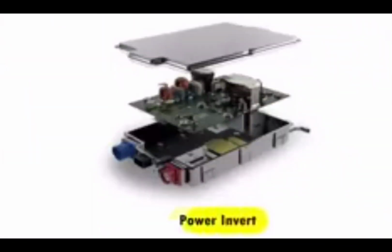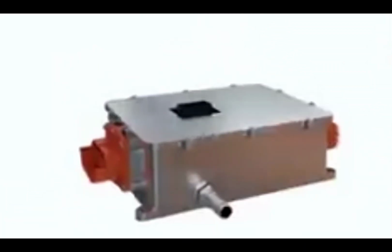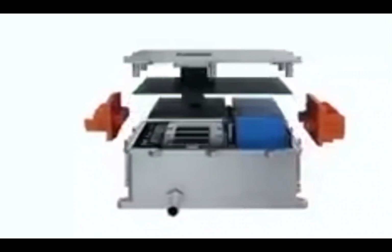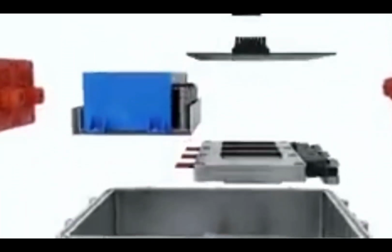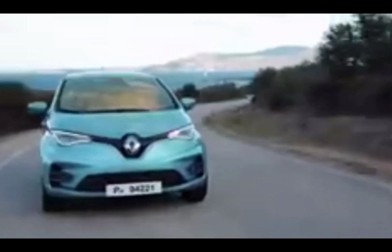Power inverter. The inverter functions to change the direct current from the battery into alternating current. This alternating current is then used by the electric motor. In addition, the inverter in an electric vehicle has the function of changing the AC current generated while braking to DC current and then using it to recharge the battery. The type of inverter used in some electric vehicle models is the bidirectional inverter category.